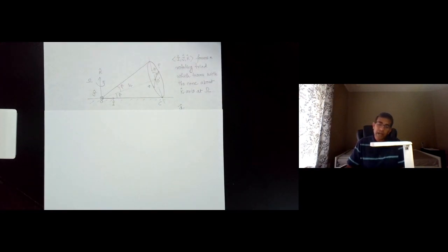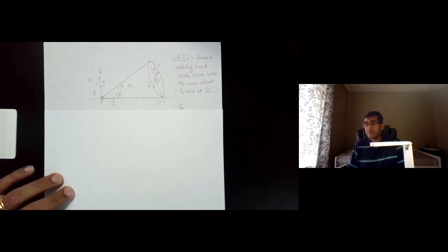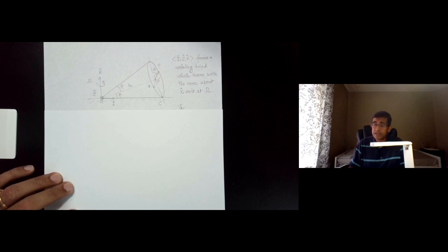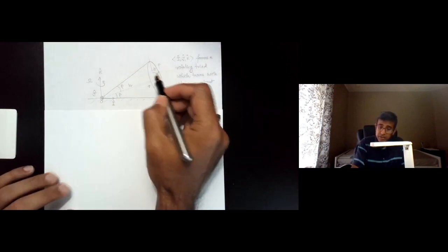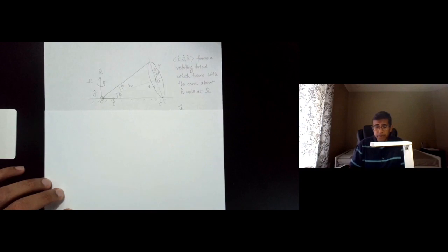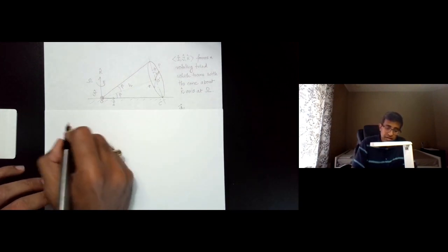And if we take these two motions separately, then we can impose the fact that the point C must have 0 velocity for rolling without slipping. And when we impose it, we get an expression for phi dot. So that's an easy way. There is also a formal way to find it, and we will show that in following videos.